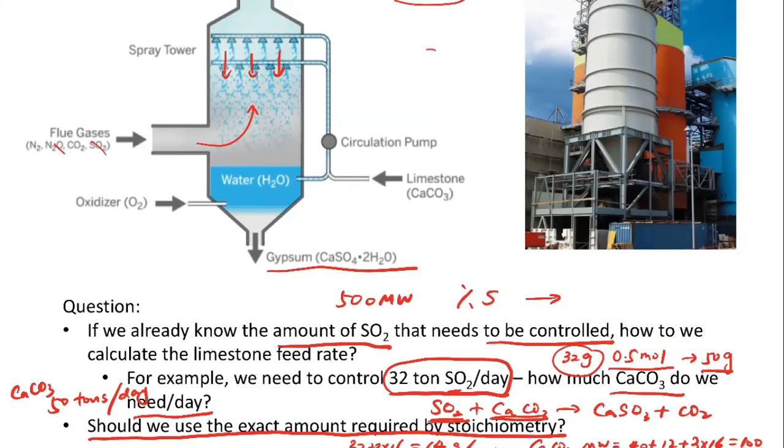So first, if we draw out the liquid, then this is a gas of sulfur dioxide. The sulfur dioxide needs to first get in contact with the calcium carbonate at the surface, or some of the sulfur dioxide needs to dissolve or get absorbed into the system. Okay, so that's going to take time, right?